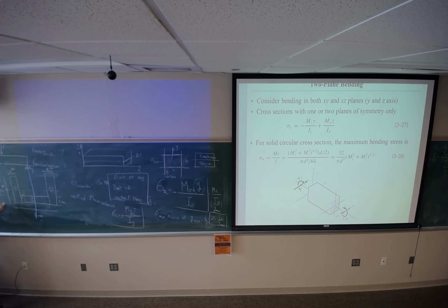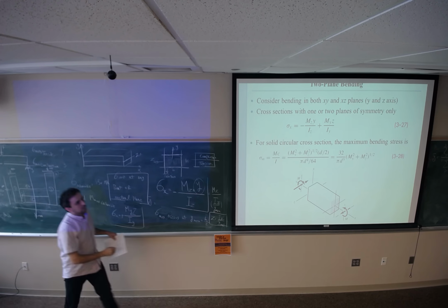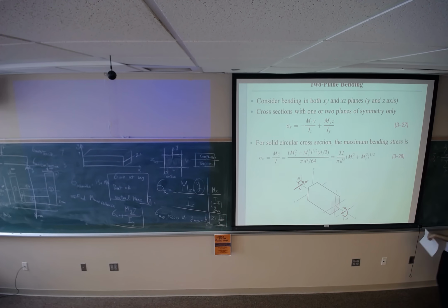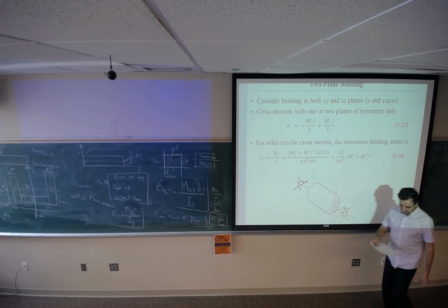A2: this is 80 millimeter, this is 8 millimeter, 8 millimeter, so this length is going to be 64. A2 is 64 times 8, and A3 is 8 times 120. If you plug in the numbers there, you can find y bar. I will continue this example on Thursday.